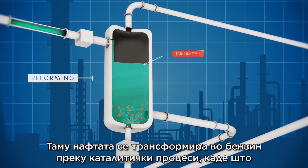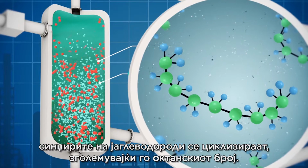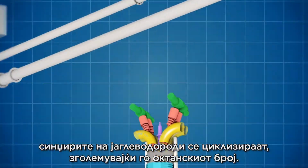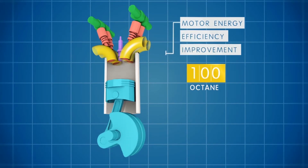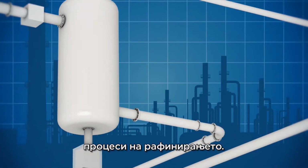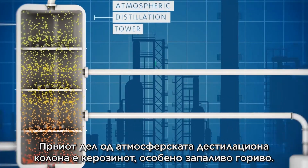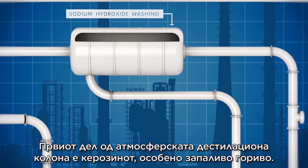There, naphtha is transformed to gasoline through a catalytic process, where the straight hydrocarbon chains are cyclized, increasing octane number. Hydrogen, which is a byproduct of the cyclization process, is used in other processes of the refinery. The first side fraction of the atmospheric distillation tower is kerosene, a particularly flammable fuel.